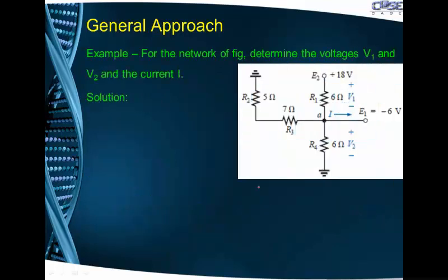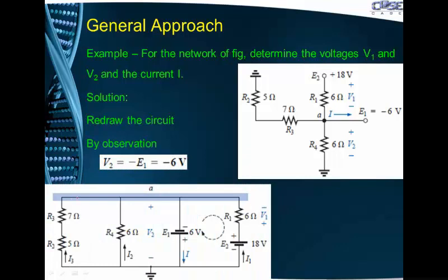For this step, first of all, we try to draw the circuit in a planar form, so that all the ground connections are set to a common point, and the batteries are indicated with the two-terminal symbol. Then at these labeled nodes, the number of connections is indicated. As you can see, this node shaded in blue has the maximum number of components connected, so it is extended with a long connection, so that the components can be shown in a planar way and a simple form.